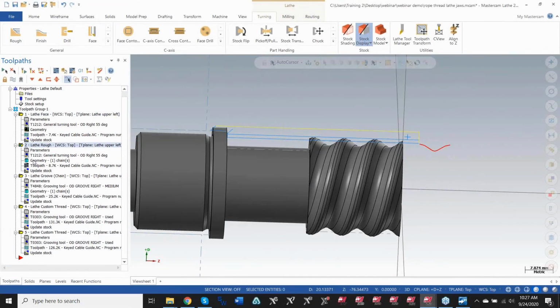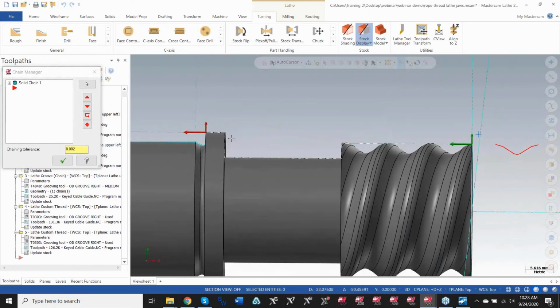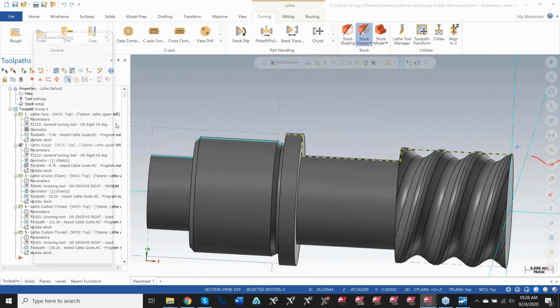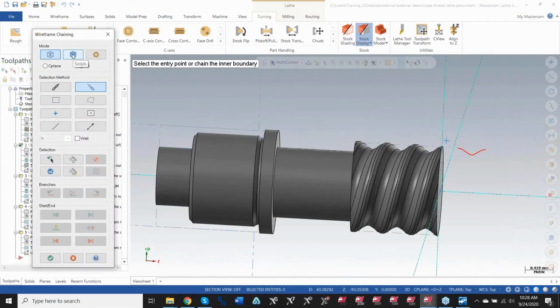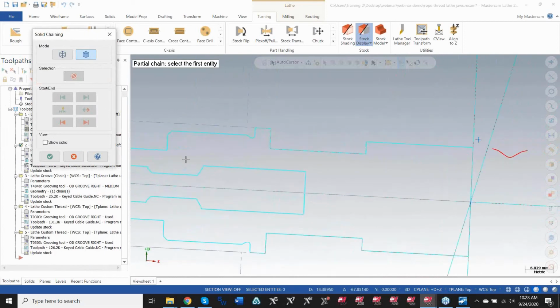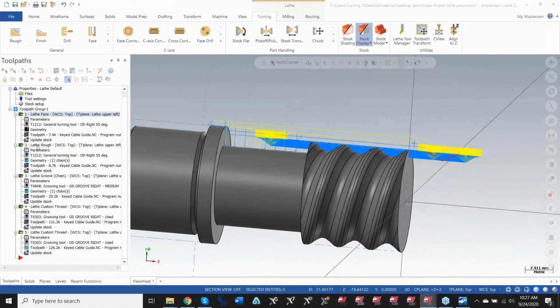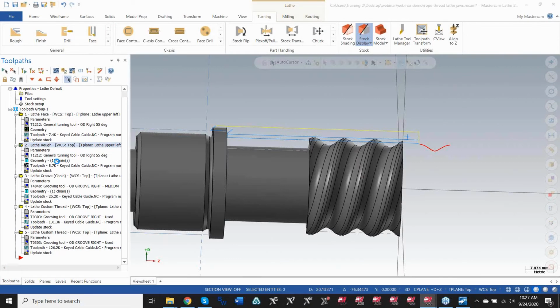Notice that there's no wireframe showing on here. So if I go to this geometry, when I made this, I used that 3D chaining. If I go to rechain all, and I click on the solid section, there's my 3D chaining. From there to there. Say OK. Of course, that's going to cause everything else to go dirty if I regenerate that, so I won't do that for now. But you get the tidbit.